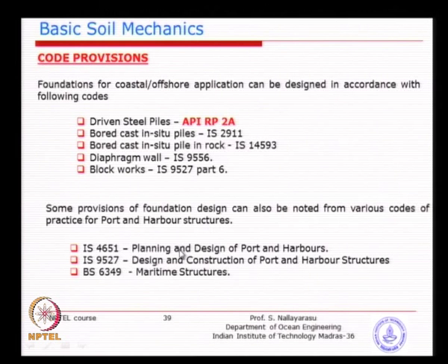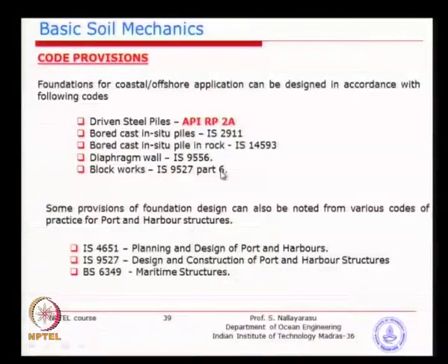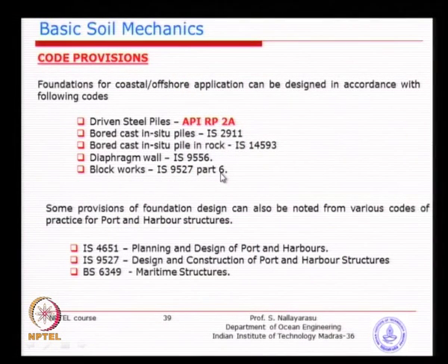In some cases, some of the codes that I have mentioned here also specify some requirements for foundations, especially factor of safety. If you look at IS 4651 for ports and harbors, the factor of safety is specified there. Similarly, IS 9527 is the construction and practice, and then 6349 is a British code, of course, for maritime structures, which is applicable to coastal structures like ports and harbors, jetties, wharves. So, you could see here collective information of codes. So, you need to use it judiciously according to the necessity and the type of structure that you are designing.